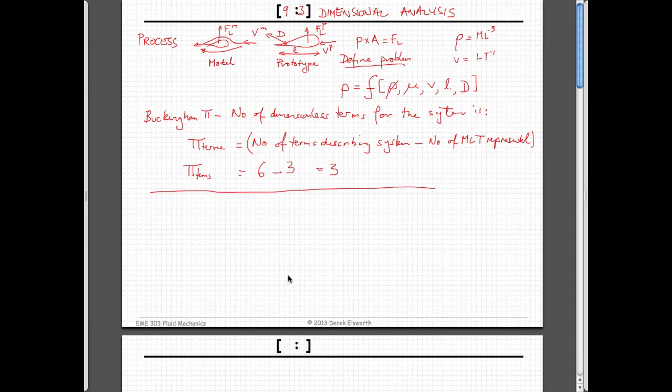without doing that. It turns out that for most fluid mechanics problems, you can describe the behavior in terms of the important variables, and non-dimensional variables tend to repeat themselves. So the first observation is what we need for similitude. In other words, what you need to have in place so that you can use the information from a model to say something about the prototype.